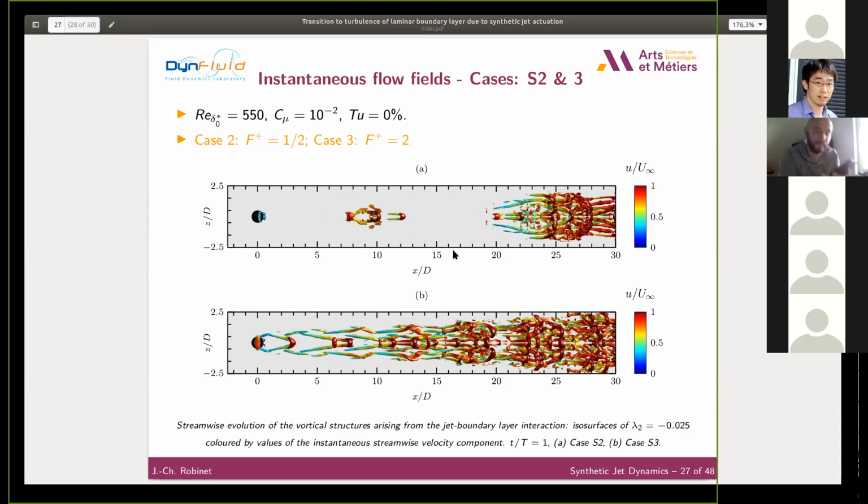I don't know, because the evolution of the streaks is not deeply affected, but the evolution of the hairpin, I don't know. Generally, it's more complex to generate a hairpin in supersonic flow, but it's possible. But I really don't know. Probably the transition is delayed, but I really don't know if we can have an additional effect. Typically in a boundary layer, you have a secondary mode if the Mach number is larger than 4.5. I don't know if we can generate a different dynamic. For a moderate value of Mach number, typically it's just a damping effect.